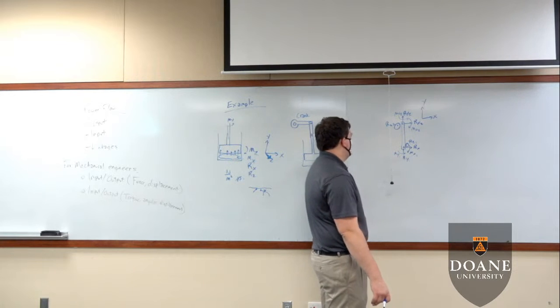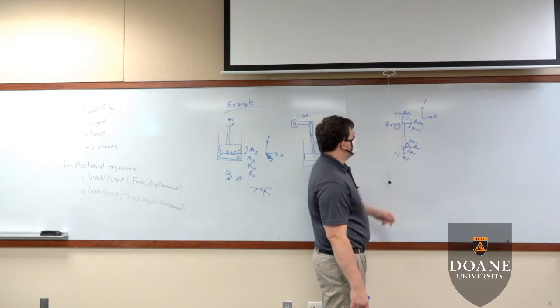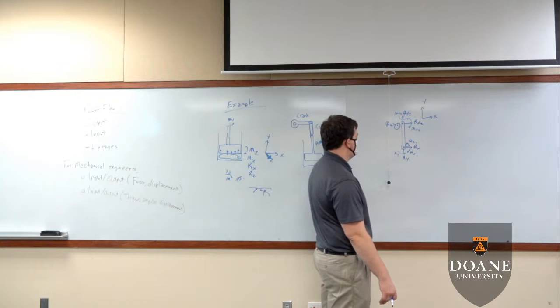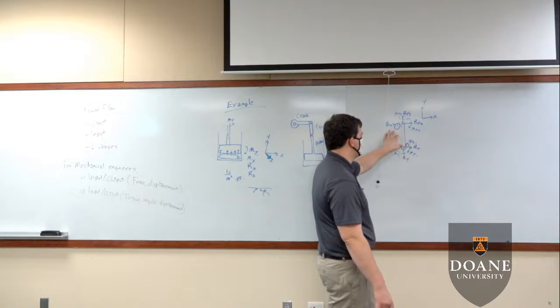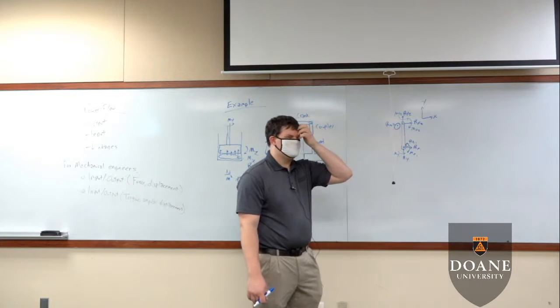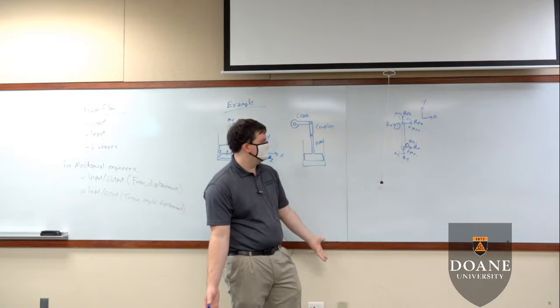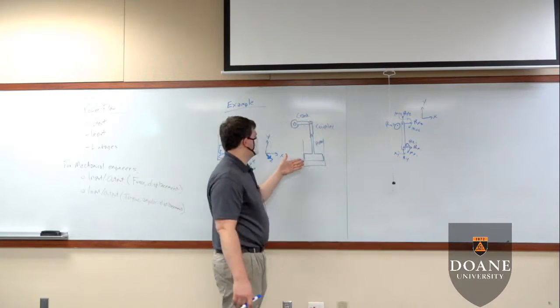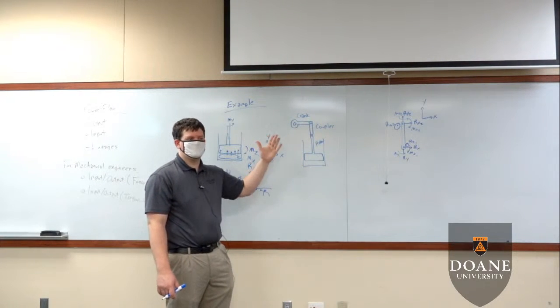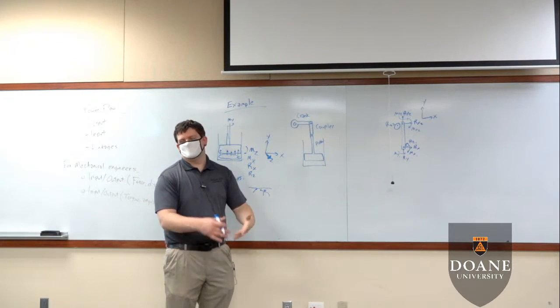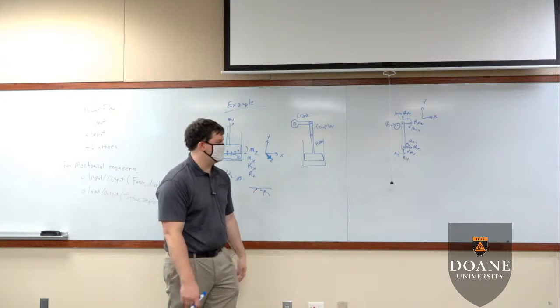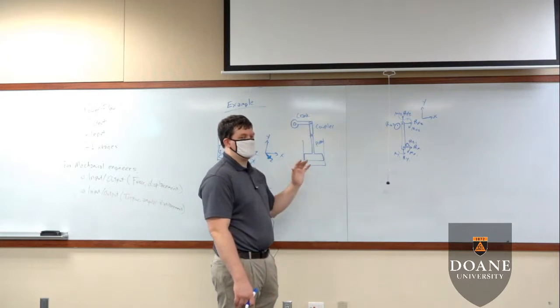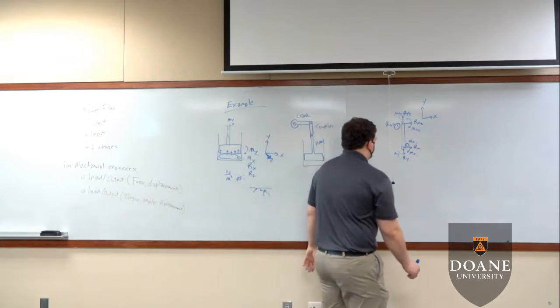Now, it is possible to have an mx value, and that mx value would happen if you have an RZ. We're going to assume that there is no RZ value because there's nothing here that's creating a force in the z direction explicitly. I mean, you'll have some based on vibrations, but it'll be small. It's small enough that we're going to ignore it, okay?